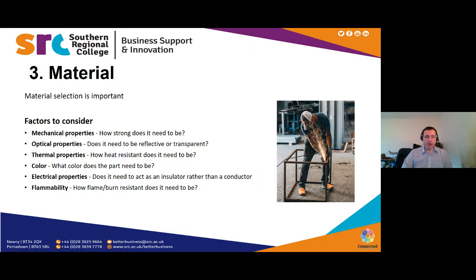Yeah. A lot of times, as I was saying earlier, if you make changes earlier on, it doesn't really affect the design process. There's always going to be changes in the design process. What you want to do is minimize the amount of design to be changed at the end. Changing the color might not necessarily be a big problem with the likes of this agricultural machine, but changing the color could have a big effect on a plastic part, because different colors may cause different shrinkage.